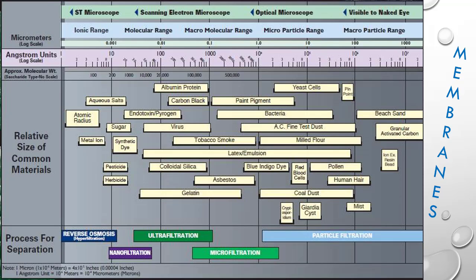And these are designed down to below 0.1 micron. These high purity cartridges are usually absolute rated cartridges for precise filtration, by the way. Nominally rated budget price cartridges that we typically see on shelves of stores do not assure that any given micron rating on that cartridge will be achieved.